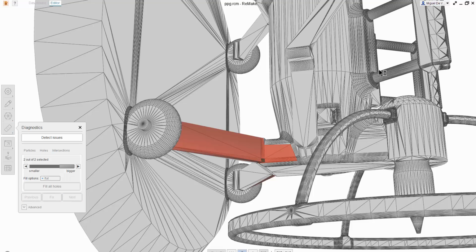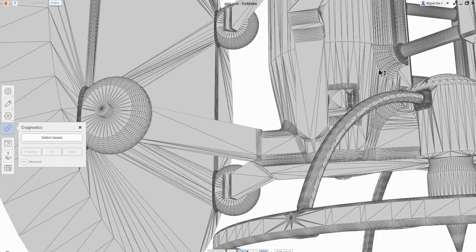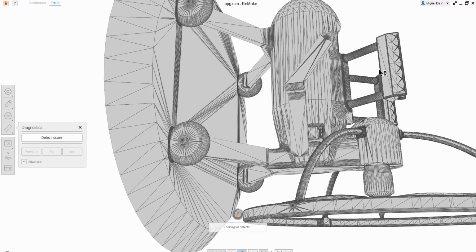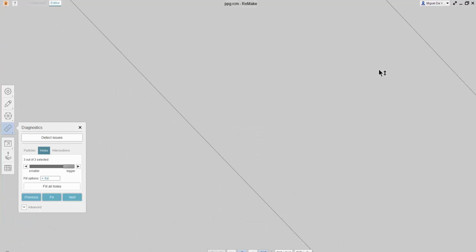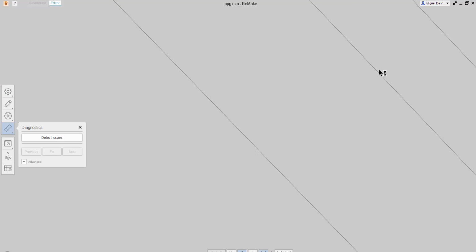What this does is that it goes through the process, fixes these imperfections as best as it can, and we're just going to keep hitting detect and fix until it says there's nothing left and it's a fixed file. So rinse and repeat. You may have to do this quite a number of times until you get a nice solid mesh. If you download something from, say, Thingiverse or MyMiniFactory, any one of those 3D printed file public repositories, I guess you could say, it's usually good enough. It's usually already fixed and is very clean and ready to use.